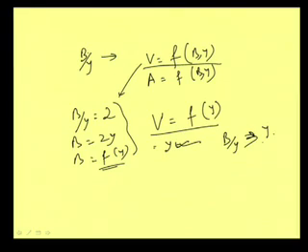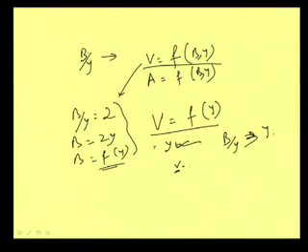So the size of the channel will be known, then we can calculate the area and find out the velocity. So this is also a procedure that we can follow once the b by y ratio is given. But the only problem is that when we use the b by y ratio, we are getting the velocity, not starting from the velocity. Once we get the velocity, we need to check whether it is below the maximum permissible velocity. Otherwise, if the velocity is high, we need to adopt another b by y ratio and try solving again.